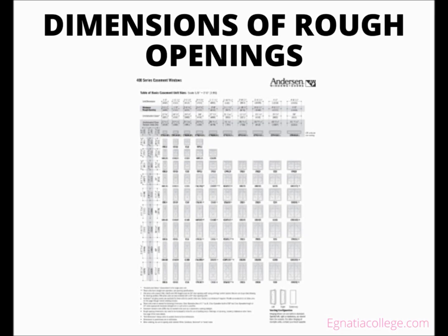If the finished doorway, the jamb, is to be built on the site by a carpenter, the rough opening size will not be available. In this case, the rough opening for swing doors can be built 2 inches wider and 2 inches higher than the door. If the door is another type, you must first determine what the finished opening is to be. Manufacturers of hardware for sliding and bifold doors specify rough opening sizes for doors installed with their hardware. These manufacturers' specifications should be consulted as the opening is being framed.